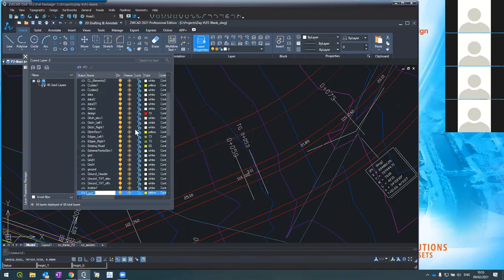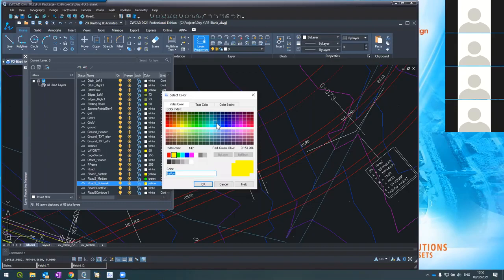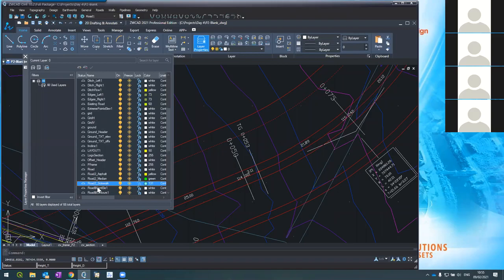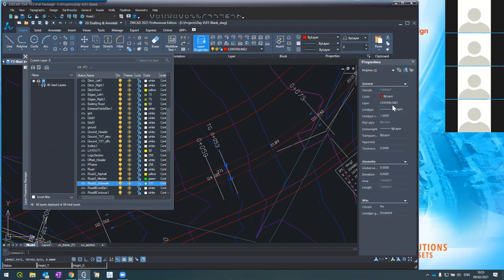And I'll do another one, I'll call it road 2 sidewalk. Meanwhile, regular CAD. And this one, I do it like this. Good, so I have 3 layers, asphalt, median, and sidewalk. So what I'll do, I'll take this and this, polylines, and change them from the regional center line, which I use for the offset, into road 2 median.